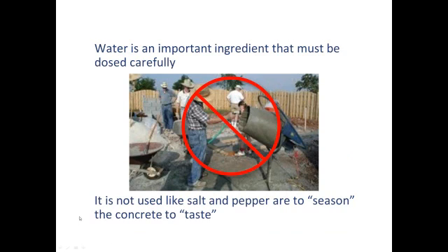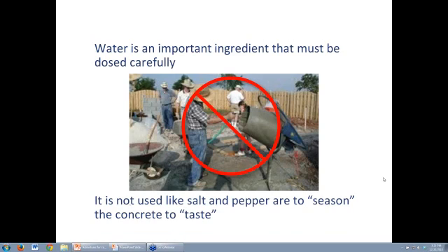I had mentioned earlier that I'm not going to talk about the primary ingredients of concrete, but water is a very important ingredient in concrete, and it's probably the most abused ingredient. And it's probably also one of the main reasons why these workability admixtures were created, is to eliminate the need to add extra water just to gain workability.